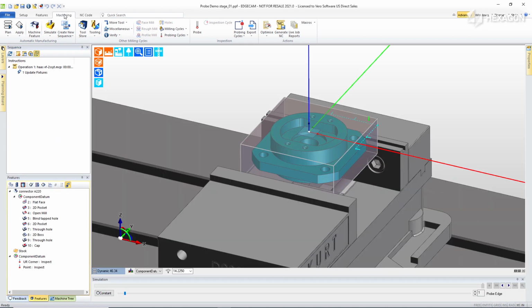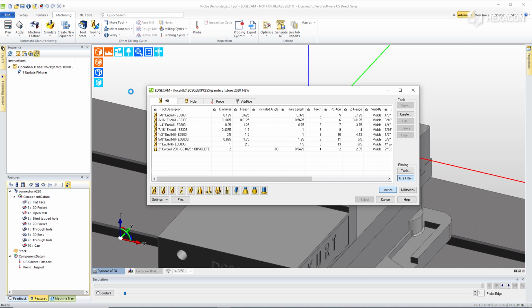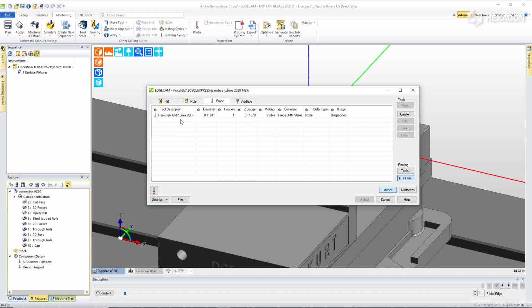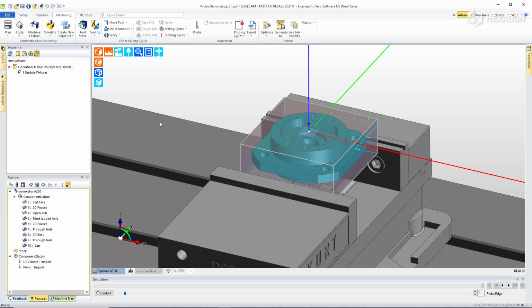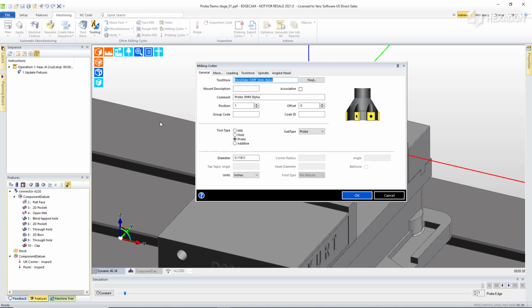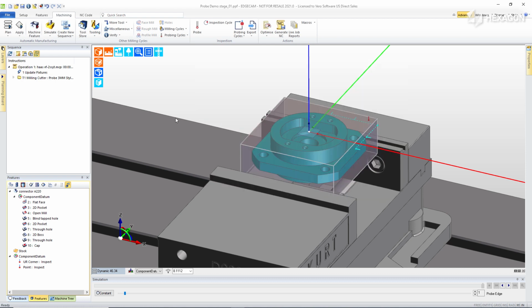There is not any tool path built yet, and so let's begin the process as normal with choosing a tool from the tool database, in this case looking at the specific tools in our current CNC machine magazine and choosing a touch probe and stylus that's already in the machine magazine. Once the tool is called down, we can immediately start with the type of work we want to do.